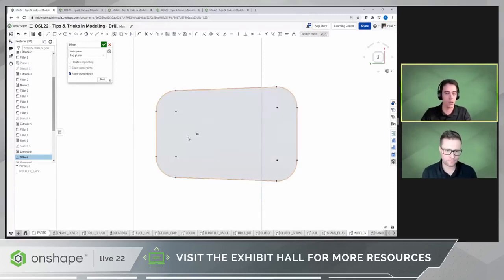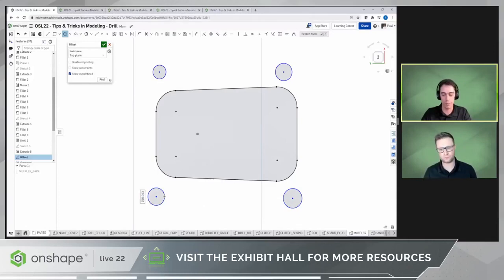For example, here, I could use the C key to start creating a couple of circles. And I have one bonus tip for you here. You can add dimensions as you go. It's a very fast way of adding a lot of dimensions quickly instead of doing that in the second step with a dimension tool. So let's define 8 for this diameter.